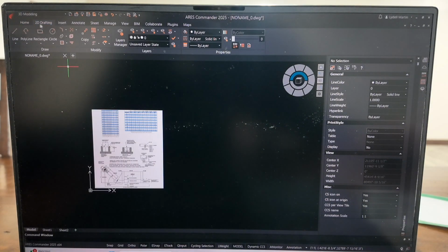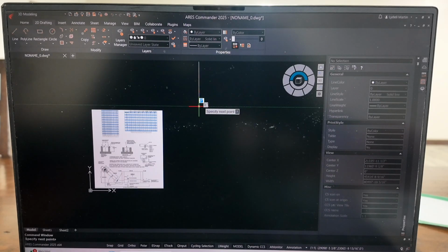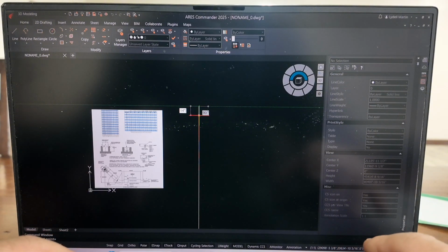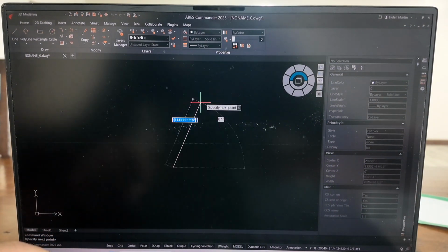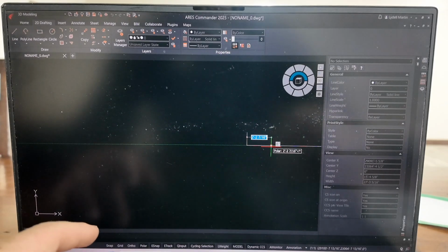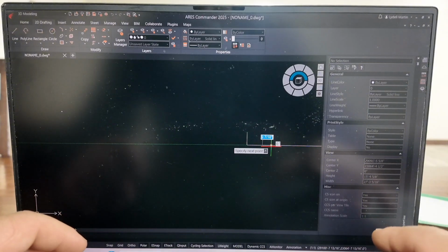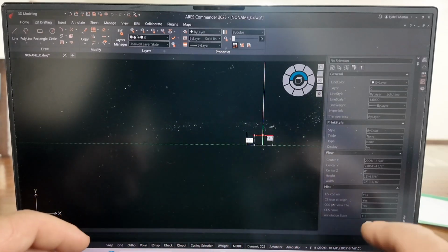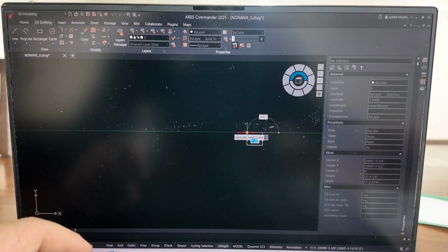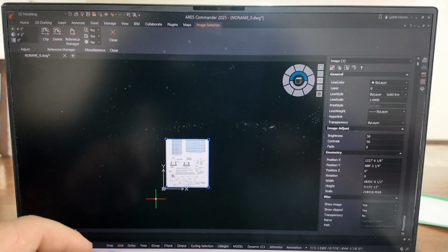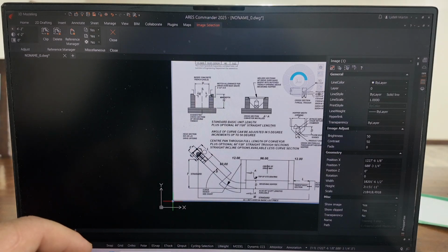So we're going to go to 2D drafting. Select the line. We're over here in the top left corner. Select the line. And we're going to go 14 inch. We type this into our keyboard. Enter. Then we're going to do 17 inch. Enter. 14 inch. And then close our box there. I'm going to make this smaller. I kind of goofed up.